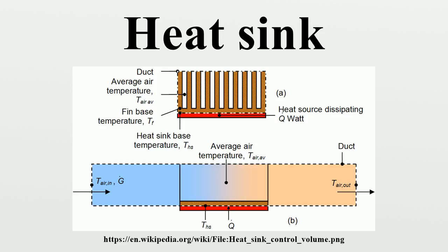Copper heat sinks are machined and skived. Another method of manufacture is to solder the fins into the heat sink base. Aluminium heat sinks can be extruded, but the less ductile copper cannot.